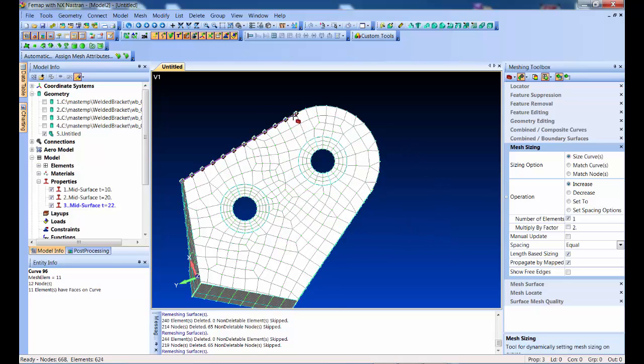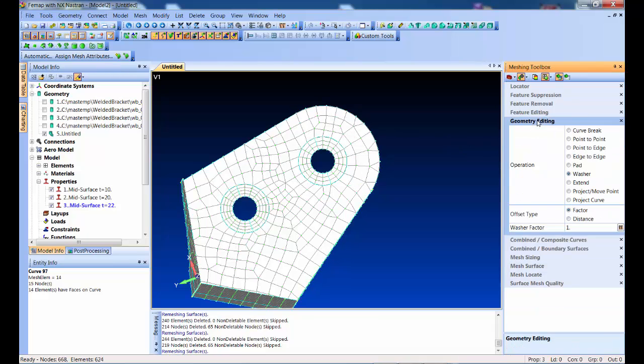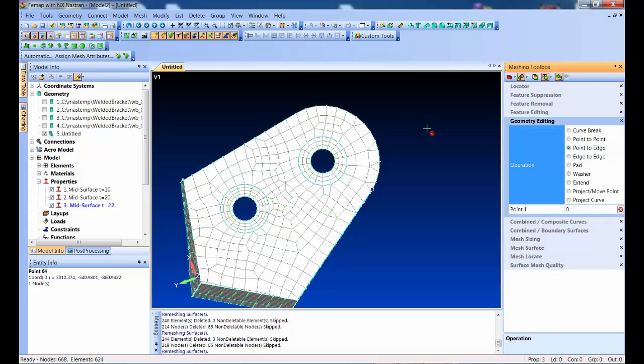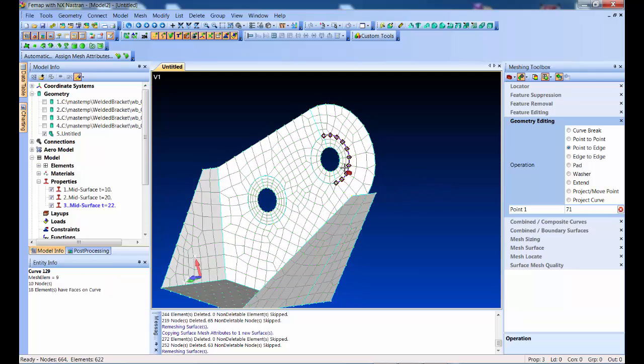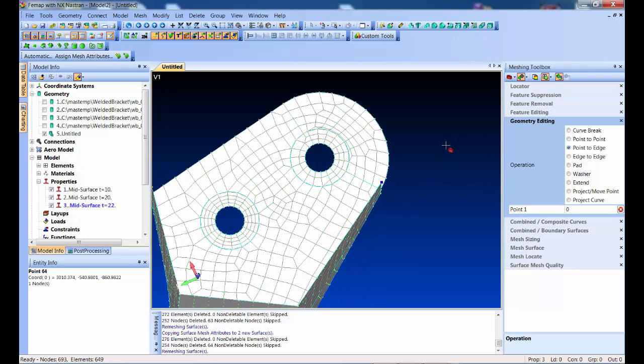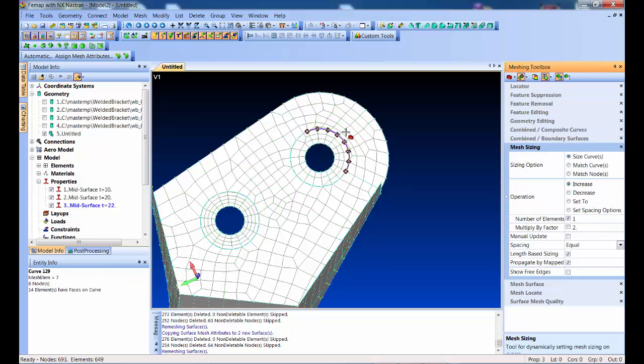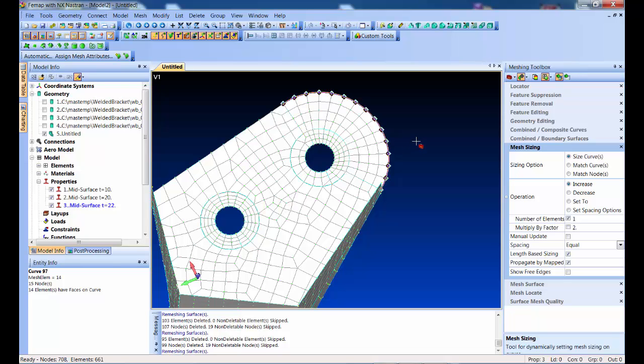If you wanted to really get a lot of control going and get a map mesh out here as well, there are some other nice tricks. I can do some more splitting, and we'll split from there to there, and we've got our point here and here. Then for mesh sizing, I can see there's 14 out there and only 7 in here, so I'll just bump it up. I'm doing it one at a time. I could just type the 14 in, but I'm not.